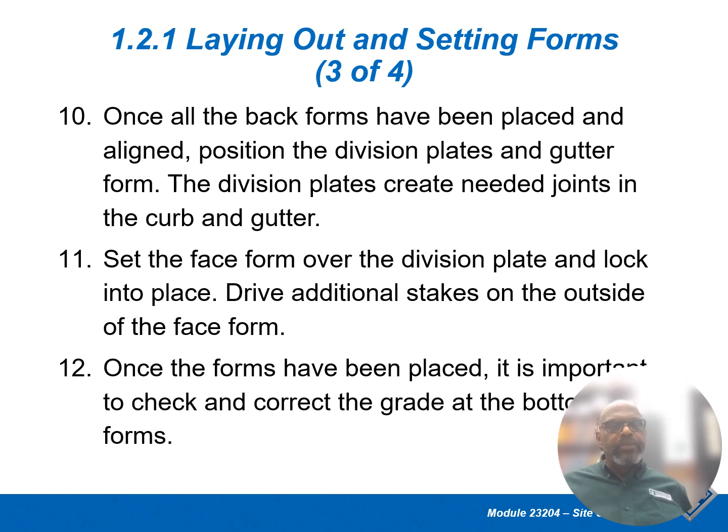Number 11, set the face form over the division plate and lock into place. Drive additional stakes on the outside of the face form.